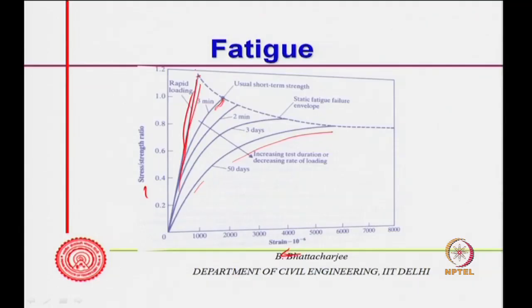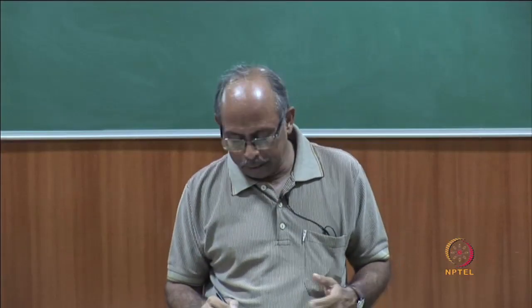So, what will happen? With very rapid loading, the micro cracks would not form, but suddenly there will be a sudden brittle failure at some higher load. So, it fails somewhere there. But if you are loading, let us say, with a 3-minute failure up to failure, which could be the case in static monotonic loading, it will fail somewhere there, not much deformation will show. It will show this if you have a strain controlled situation. So, a kind of what we call strain softening would occur: as the strain increases, the strength it can carry is lower.